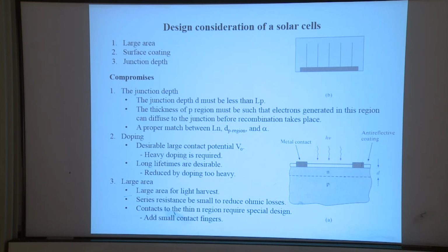If you know more detail, you know that the depletion region will occur on the low doped side. Since the N doping is very heavy, it will not develop much depletion region. Most of the depletion will occur on the P side. That means you only need a very thin layer to make a p-n junction.